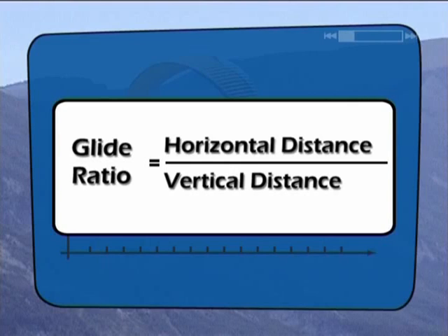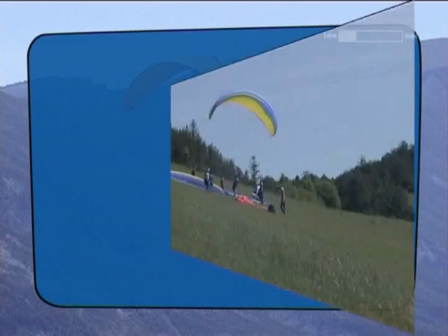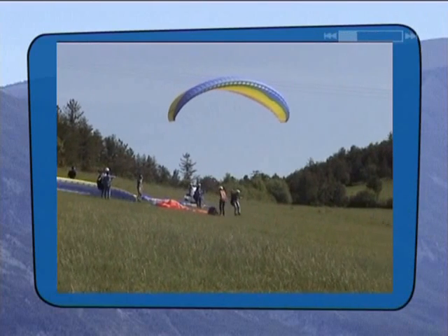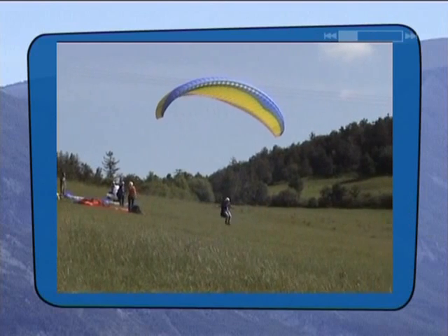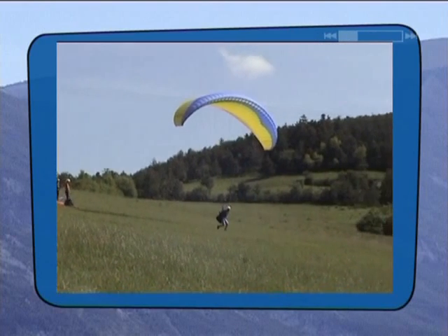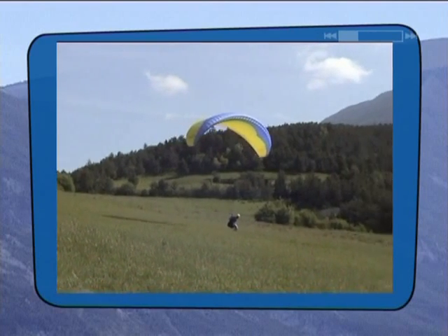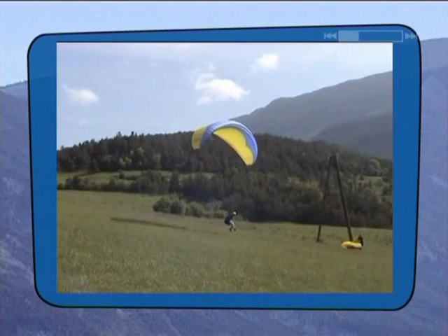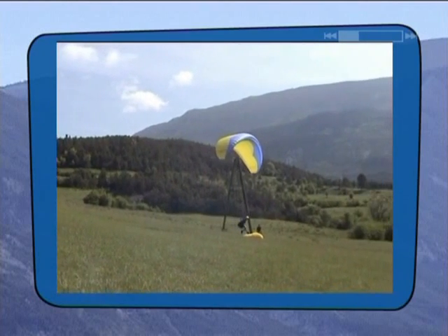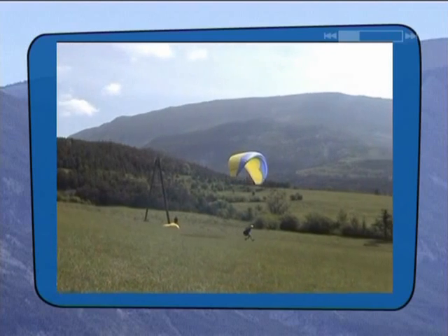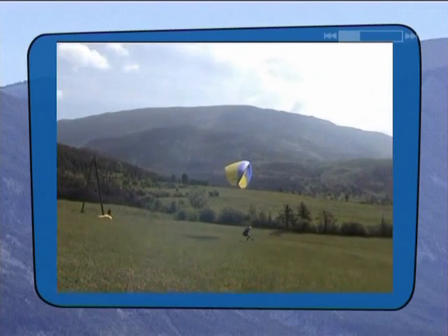We'll see later on in the flight chapter that the wind or micrometeorology can influence the trajectory. The distance covered will vary, and in this case we'd refer to its glide ratio. Let's go back to the example with our student. He can't lift off because his lift-to-drag ratio is too close to the angle of this slope. For launches, we'll need a hill whose slope is steeper than the lift-to-drag ratio of our wings.